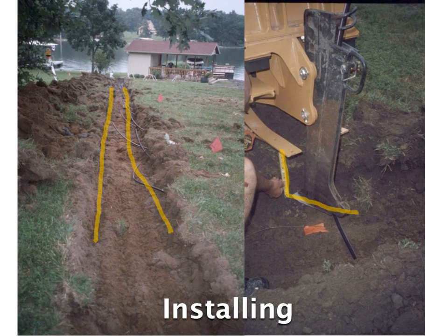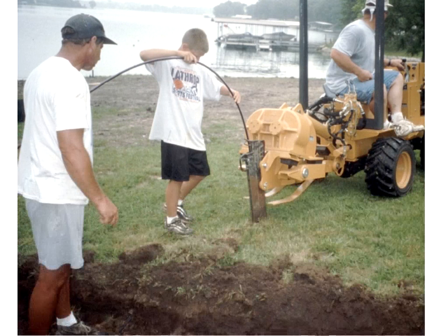Sometimes you might need somebody to put their foot on that piece of pipe, in order to stop it, to pull it through when you get started, because otherwise it's got no force to hold it back until it gets going. Once you're through three or four feet, you can take your foot off, because obviously there's enough friction then to hold it. This is, of course, the best way to go, because it keeps your overhead way down with child labor.